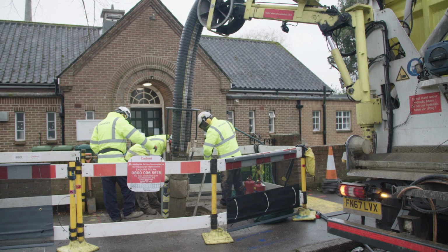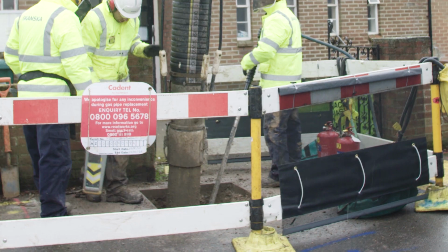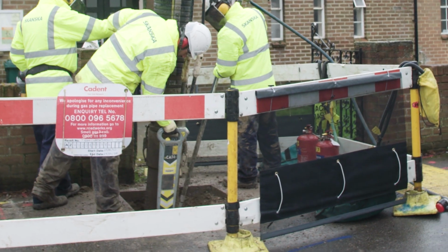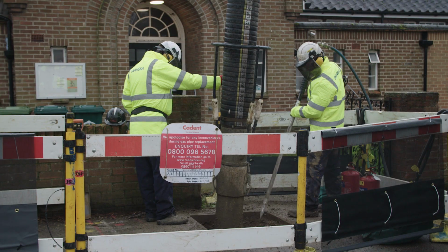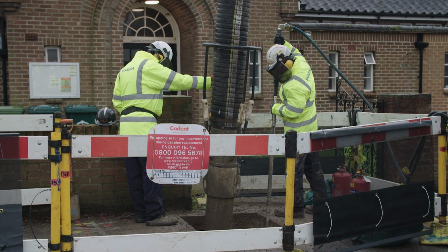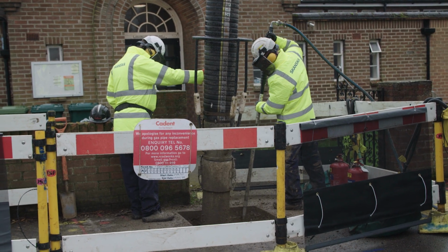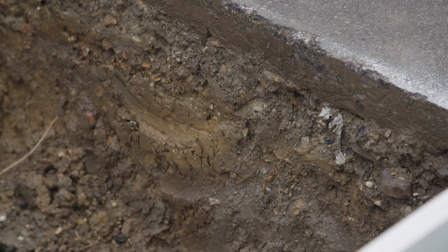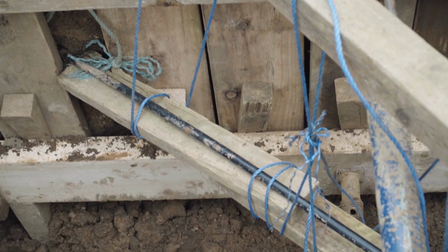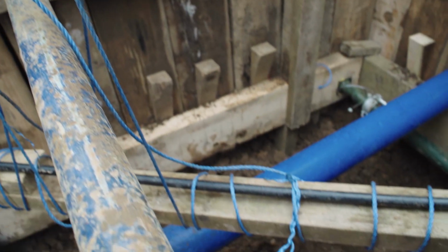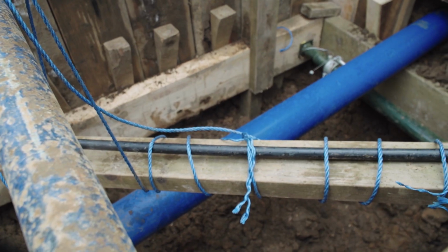The excavation must be retraced a minimum of every 300 mm to ensure you get the most accurate position of any unexposed underground services. When close to utility, an air lance or safety shovels can be used to support the safe exposure of buried assets. During this, the ground conditions should be continually assessed for suitability. If the excavation exposes cables over a distance greater than 1 meter, then support boards will be installed to prevent any bowing damage occurring to them.